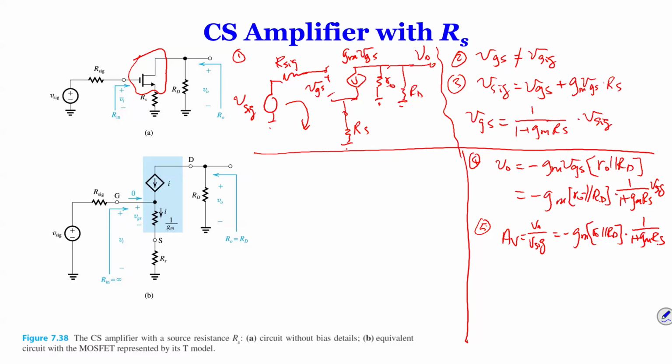with the pi model. But of course, in the future, if it's a BJT, it becomes more complicated, because that's no longer an open circuit, you have r pi over there. And the current is no longer like GM times V pi, but actually it's IB plus IC, which goes to IE. We're going to get to that, probably not today, but we'll get to that point. So that's what we did with the pi model.